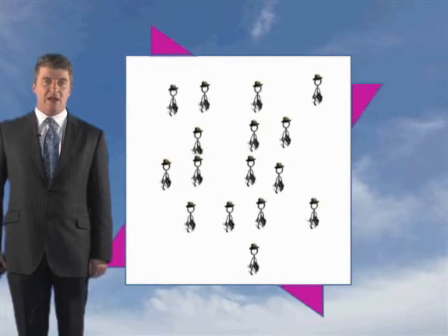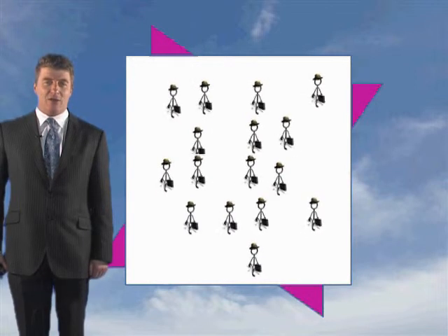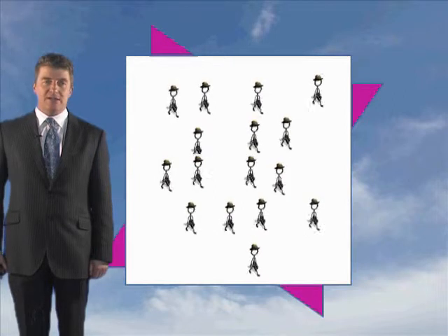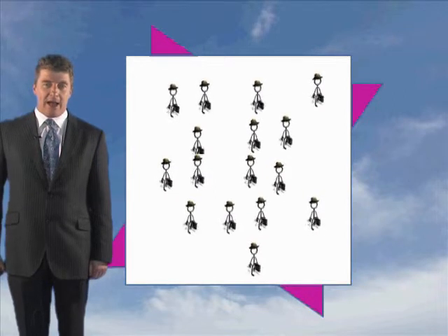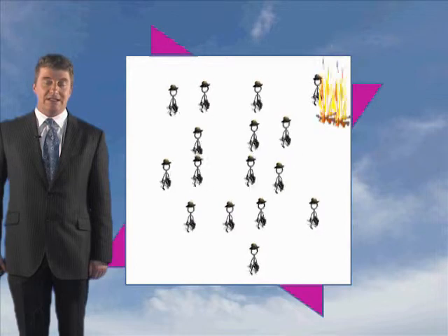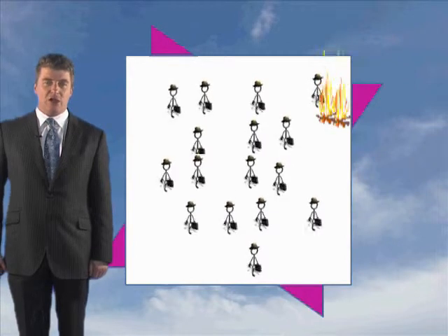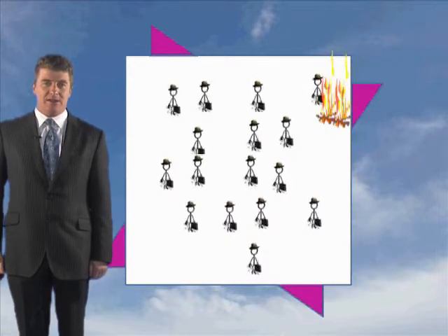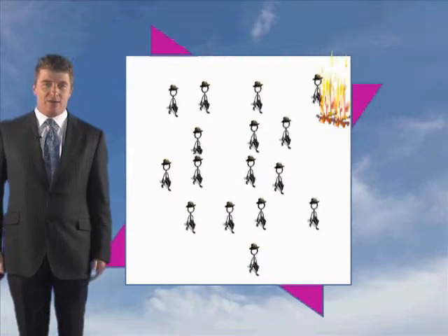And our calculator, if there's more than one exit, takes out the greatest exit width, which it should do. In other words, if it's got 4 exits in a bar and you've got 4 2-metre ones, it will take out the biggest. So it lets you quickly and accurately determine the parameter for aggregate exit width. Do you see how easy it is to determine these parameters quickly and accurately with our calculator?